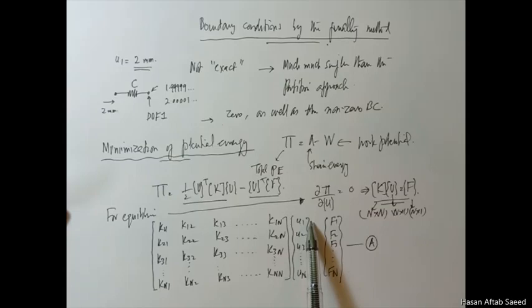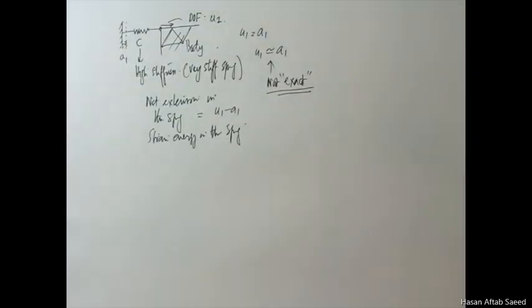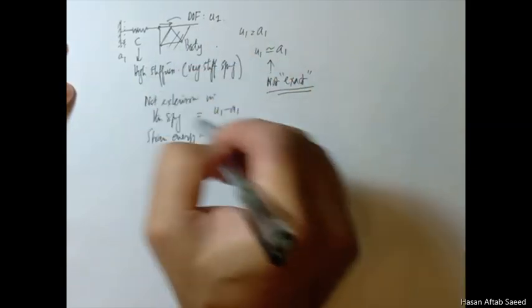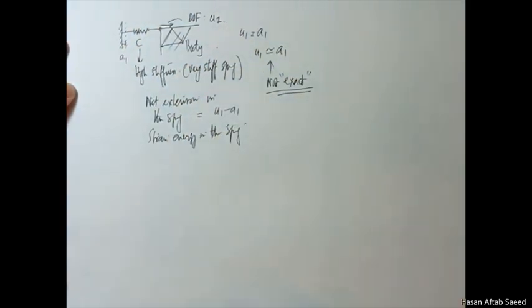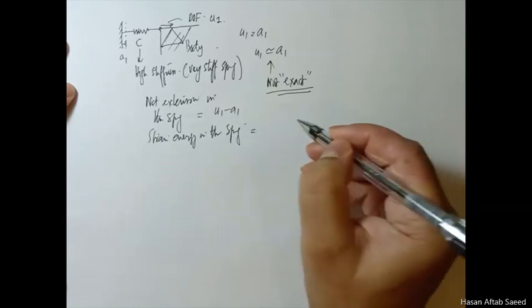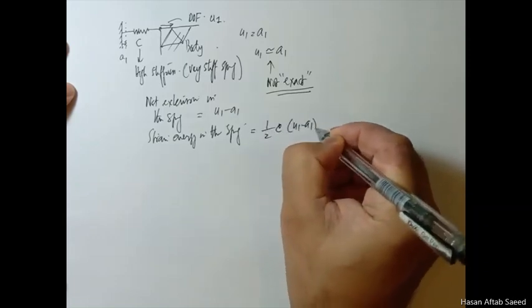You didn't use a spring or anything like that. So this covers that. But now that you are going to use, this is your system, but you have added a spring here. Now the strain energy in the spring also must get added to your system equations, and that is nothing but, strain energy is simply nothing but 1 over 2 C (u1 minus a1) squared.